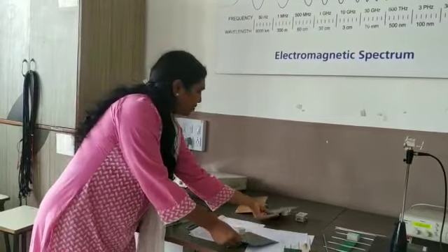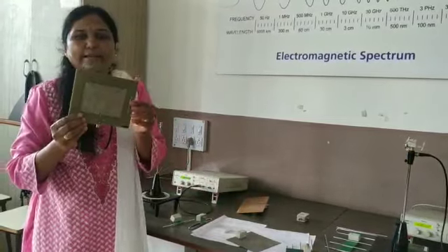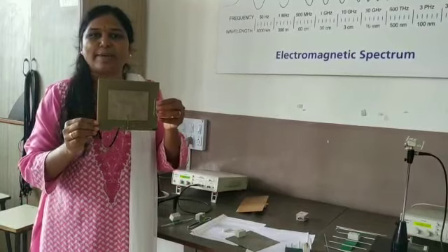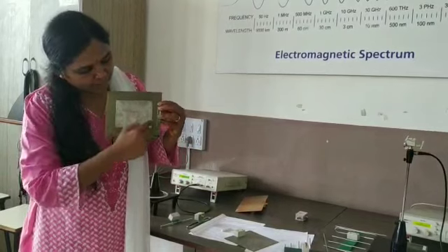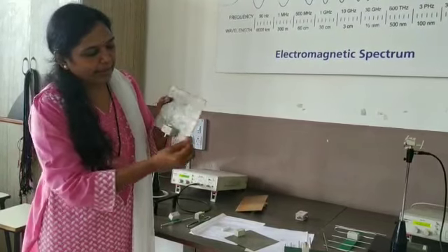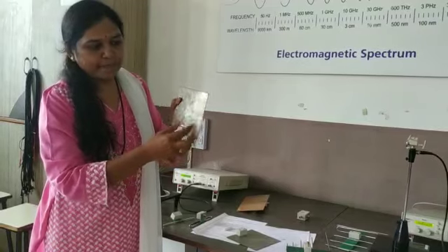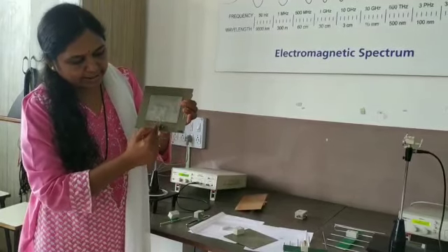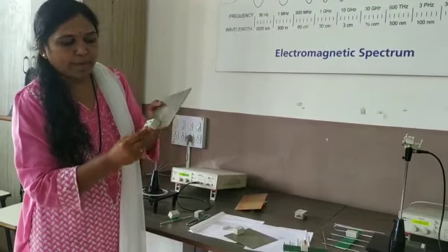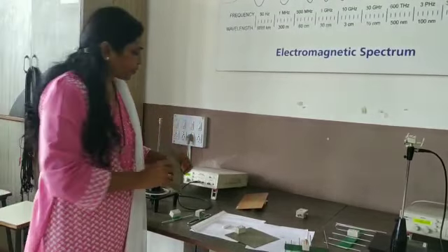Then there is one more different microstrip antenna, which is nothing but the rectangular microstrip antenna. Here you can observe this antenna is a rectangular microstrip patch, and again the backside is the ground plane, and here the inset feed excitation technique is used to apply the excitation signal.